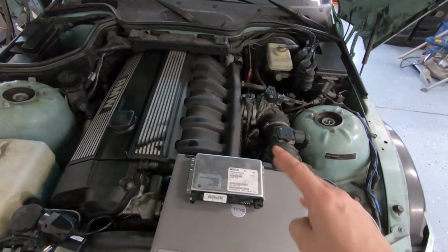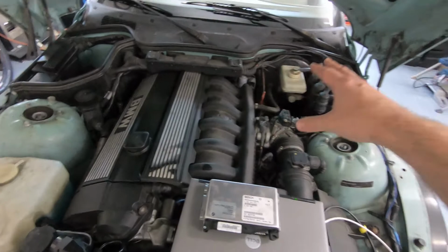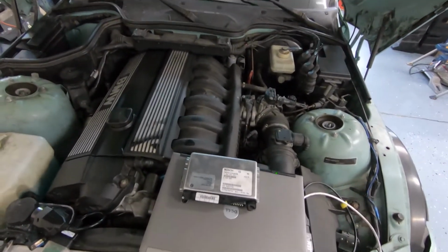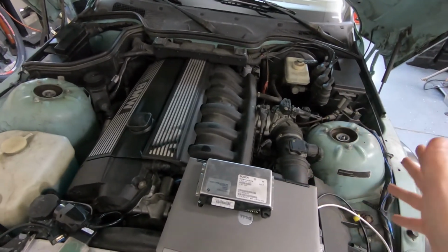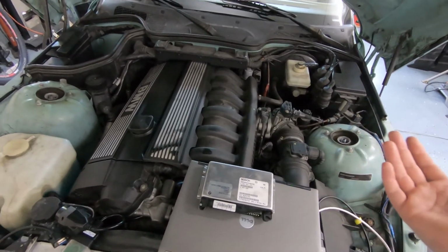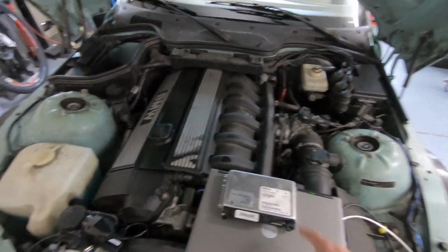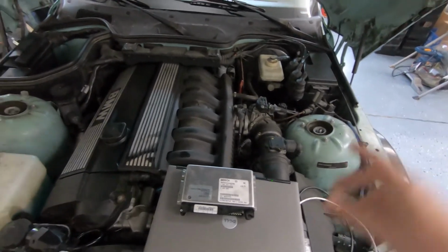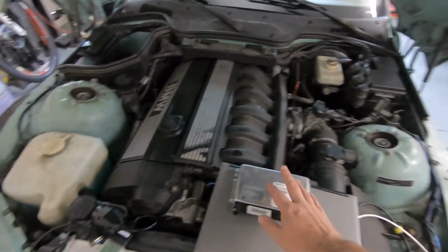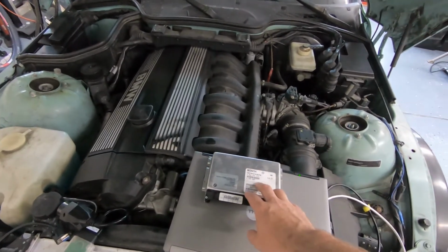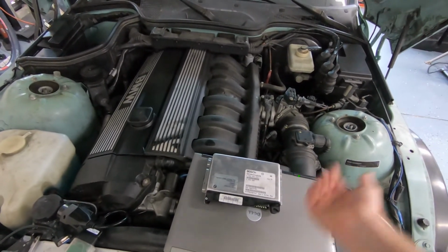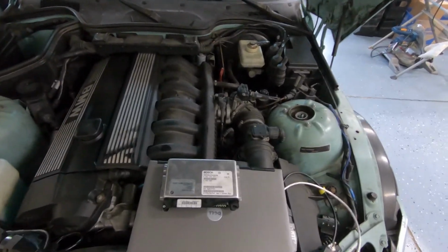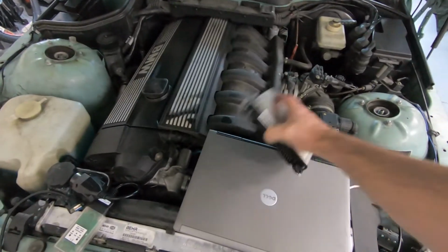So my end goal with this was to get the ASC working again, and then no engine control module codes. So that's where I'm at today with the coding. But I've seen some E36 guys just removing that chip and then removing the light bulb in the instrument panel, which, like I said, when I left the control module in, the engine wasn't happy. So with the control module completely out, ASC wasn't happy, but the engine was, and I'm more concerned about that. So where do we go from there?